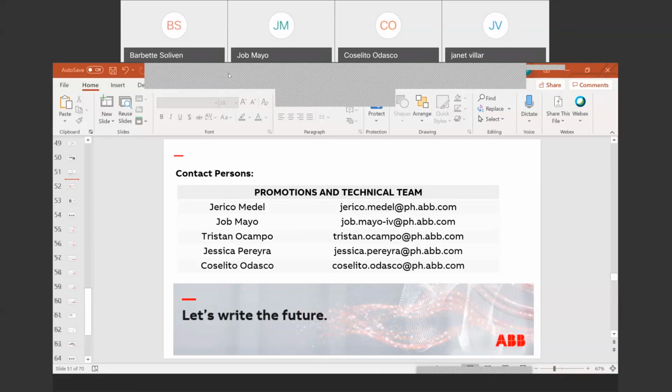So for DC applications, the standard specifies that IEC 60947-2 is applicable for both AC and DC applications. Primarily, it's used most of the time for renewable energy, for solar, residential facilities, and in some cases it is also used for railways, for train stations, wherein there's a control signal or control circuits within the panel boards.